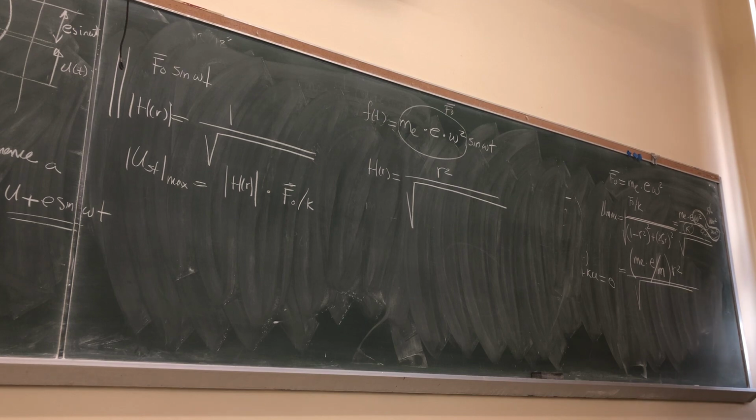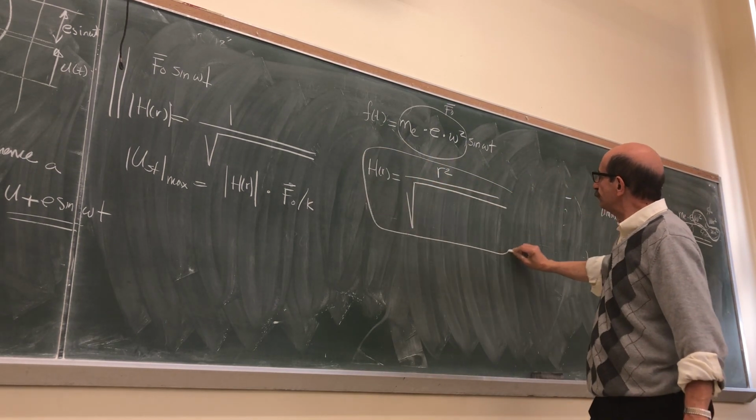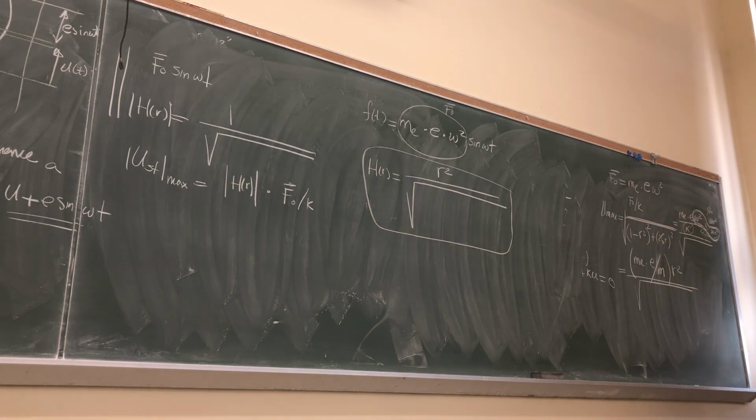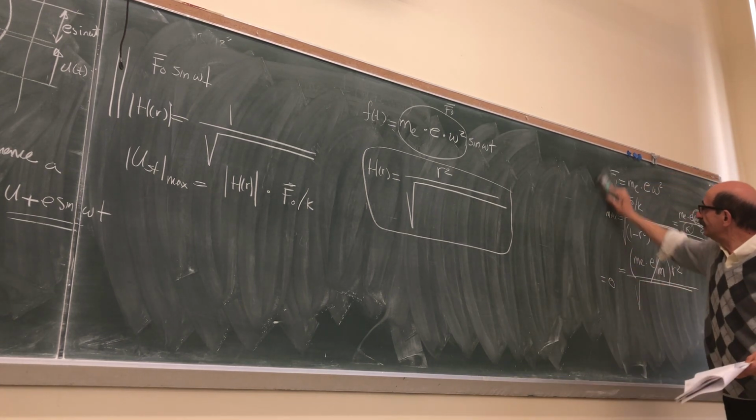From this relationship, this is the frequency response function in the case of rotating unbalance. Yes? That equation on the bottom right, this one? That's supposed to have omega squared over omega n squared in it too. Yeah, the omega over omega n and square, I replace it with r, right? That's the ratio. So if you substitute, this omega n squared is k over m, k and k go, and that's what you get.